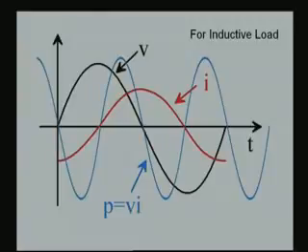So, you have the sinusoidal, first the negative half coming in, and then at the 90 degree point corresponding to the voltage waveform, you see that the current is 0 at that instant, voltage is maximum at that instant, and the product is 0 at that instant, as you see in the blue colored waveform.